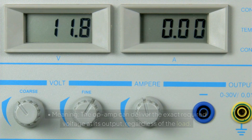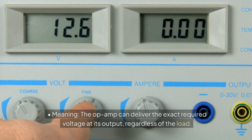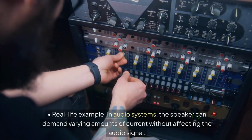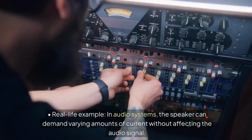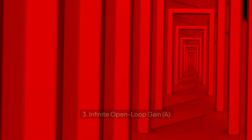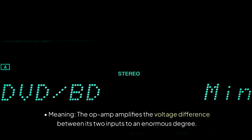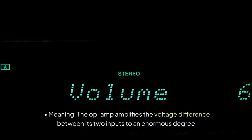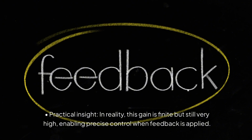with the measurement. 2. Zero output impedance, meaning the op-amp can deliver the exact required voltage at its output, regardless of the load. A real-life example: in audio systems, the speaker can demand varying amounts of current without affecting the audio signal. 3. Infinite open-loop gain, A, meaning the op-amp amplifies the voltage difference between its two inputs to an enormous degree. Practical insight: in reality, this gain is finite but still very high, enabling precise control when feedback is applied.